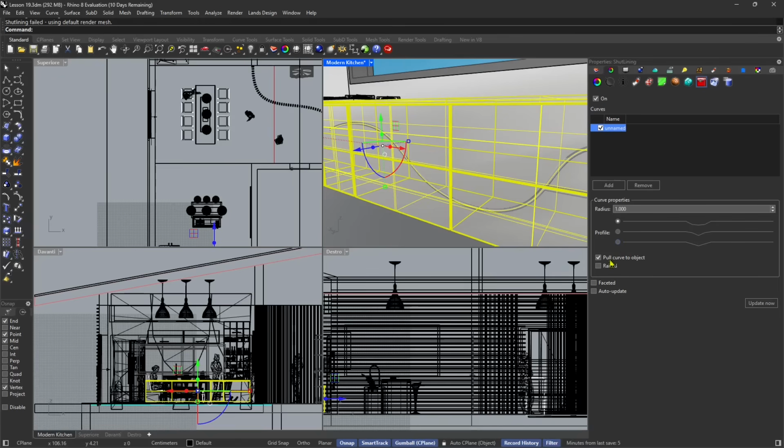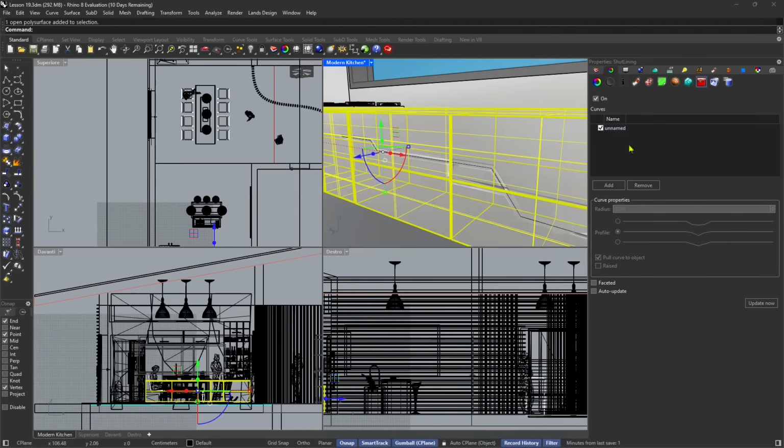Also, you can carve as we are doing here, or you can make it raised, meaning that it's gonna go like a relief. Okay, so try to put it like on smaller objects, otherwise it will be like too heavy. And here you also have other options that you can try, but I'm just gonna turn it off. This was just to show you quickly. I also change the type of line, and in my experience, it gets really slow when you have really complex objects. So try to put it in smaller parts, not like in the whole kitchen like I'm doing right now.